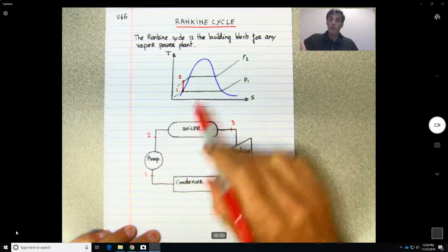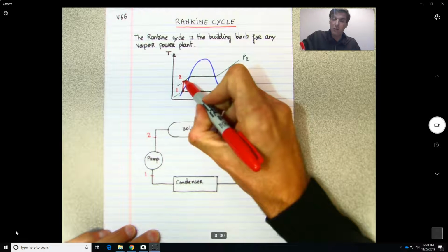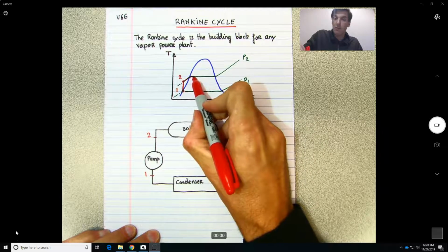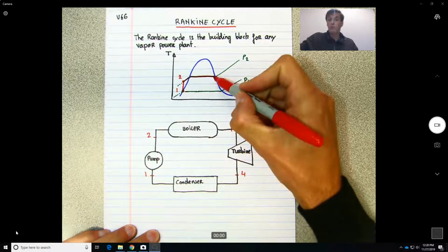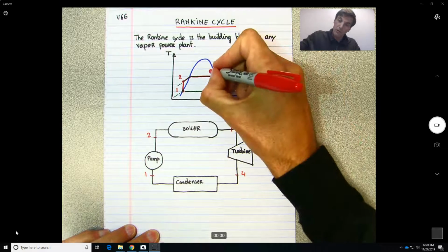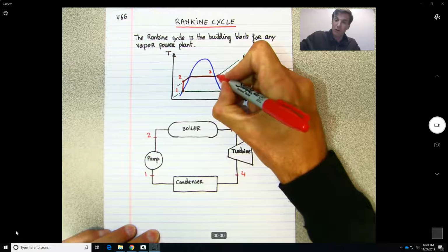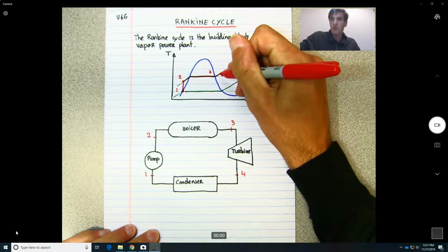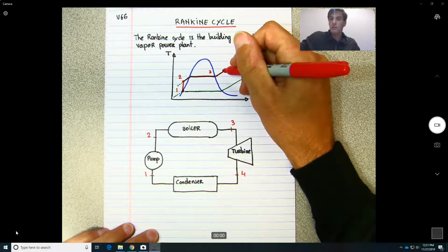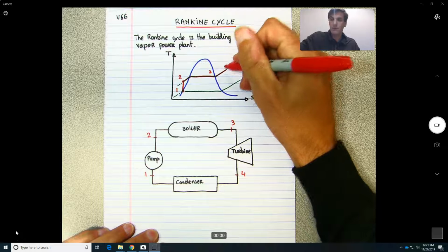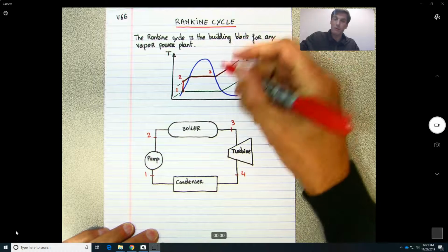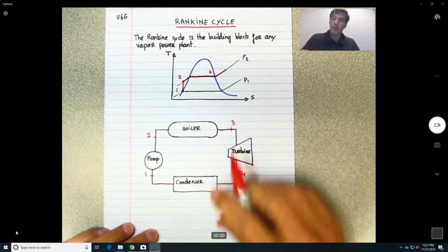So what's going to happen in the boiler? You're going to heat it. It's going to go to saturated water over here. It's going to still be heated, and the minimum temperature you need would be the water to be here saturated vapor. But you will see that in most cases the water will keep going up. Maybe that figure is not that good. Not good at all. But I mean, anyway, it will still be going up over here. We'll see that in another video.